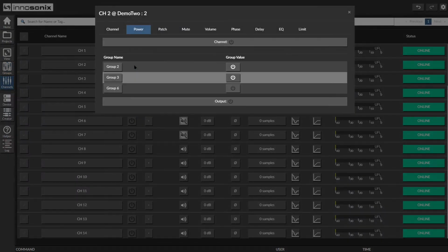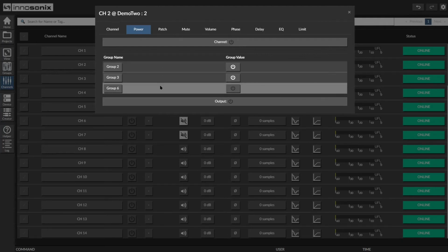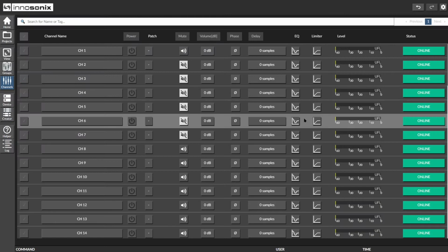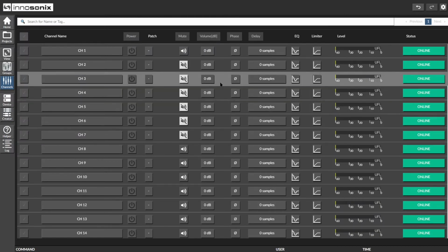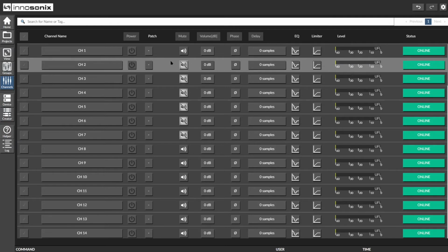A channel that is linked to a project device, which in turn is successfully connected to a power amp in your network, will receive the constraints for every parameter from that power amp. Maxx-Remote will then instantly warn you whenever you try to set values for any parameter that lie beyond its constraints.